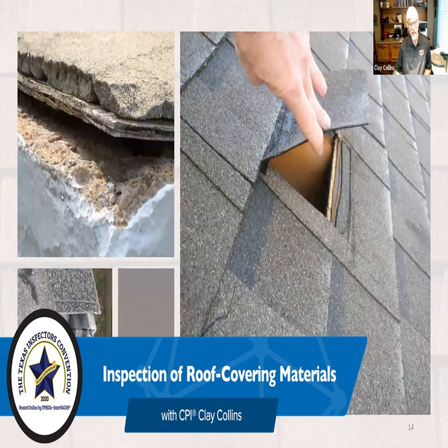Color. The color of the roof is going to impact how the sunlight reflects, because darker colors absorb heat, lighter colors reflect heat. The majority of the colors that we see are a little darker than tan, they're brown, but you can't always expect that. There's some homeowner out there that decides that he would really like a black roof. That's going to absorb the heat. It's going to affect the roof. Now, I would hope that if a manufacturer is going to design a dark roof, he is going to design that dark roof so that it will handle all the heat that might be absorbed.